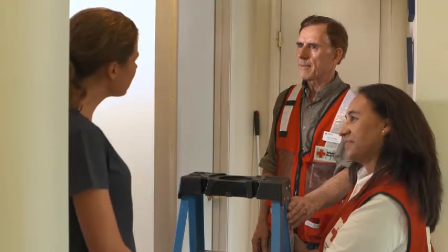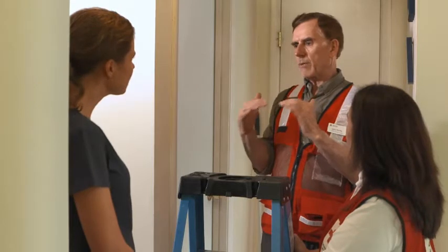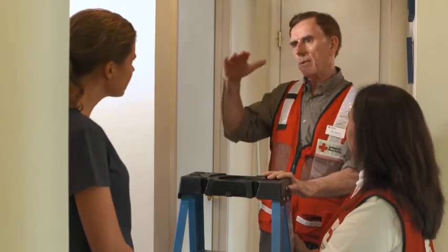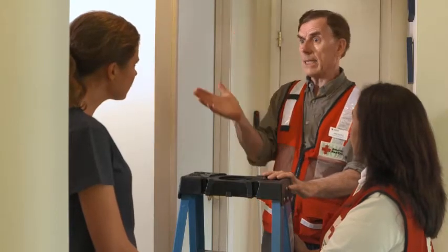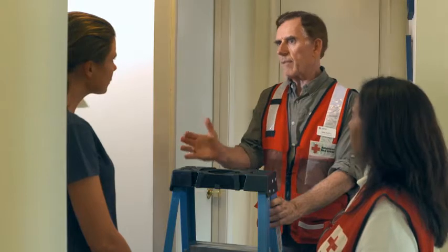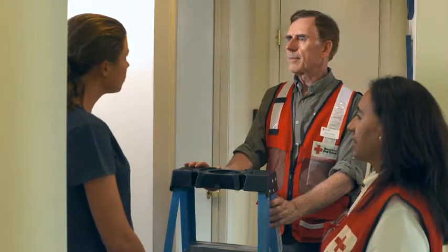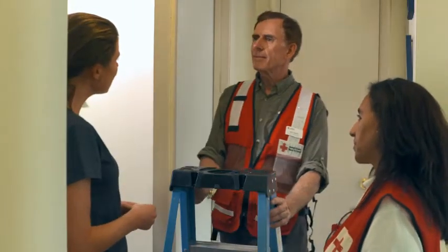No, that's the only smoke alarm we've got. Okay. At a minimum, we want to make sure that we have a working smoke alarm on each level of a home, and that would include the basement, and it would exclude unoccupied attics and crawl spaces. Do you have any other levels to the home, or is it one level? We don't have any other levels, and we are one level and no basement to worry about.